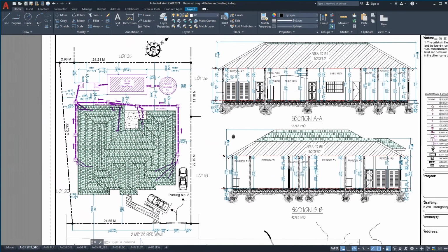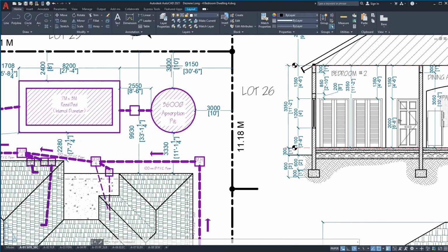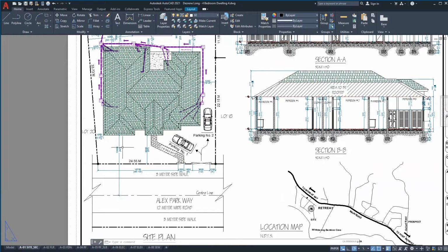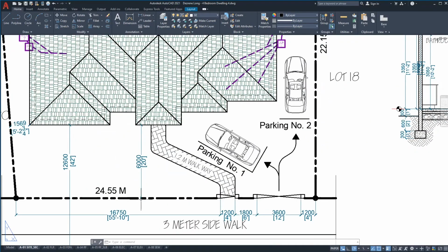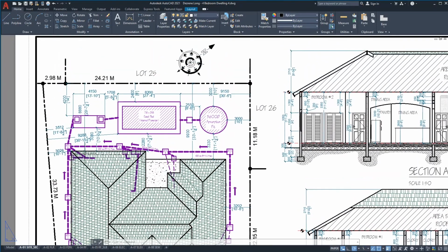Now you have the side plan here. Here's the side plan. The side plan shows how the house is positioned on the building. It also shows the sewage details and how the sewage system is laid out on the building, showing the various distances. The center of the building from the front of the building from the center of the road. The front of the building is known as the building line, where it starts. The front of the building to the boundary, the sides of the building to the boundary, the back of the building to the boundary, the distances